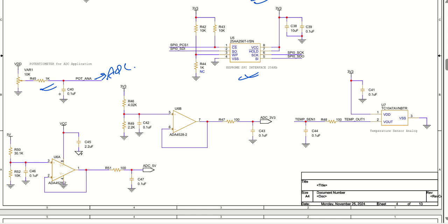Now coming back to the testing of your power supply level, 5 volt is tested using a voltage division, and then we have the op amp as a buffer, and after that we have one filter, and then it goes ahead to your ADC 5 volt measurement.